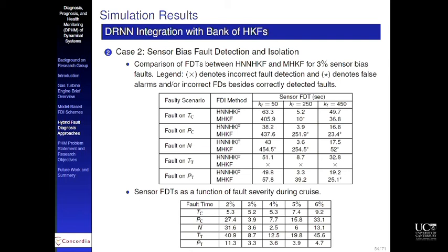When we go to nonlinear filtering, one of the advantages that the unscented and particle filters try to introduce is that this linear Gaussian assumption is no longer required. Even if you have non-white noise, these methods are able to handle it, whereas the common linear Kalman filtering methods will not.